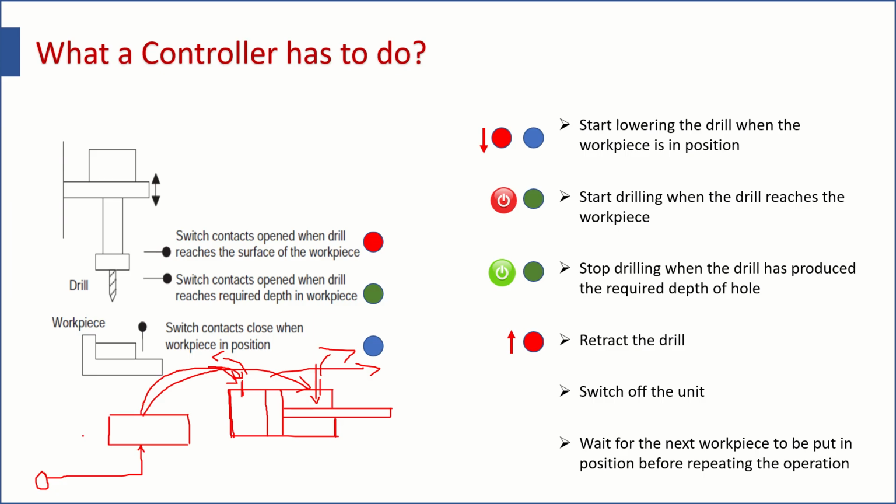So in this way, by changing the condition of a DCV, that is direction control valve, this piston will be moving either in forward motion or in reverse motion. So such to and fro motion of a cylinder, if it is required, then you need such type of valve, which is called as DCV. Why it is called DCV? Because this is direction control valve, so that the direction of the piston can be controlled. Therefore this is called as DCV.